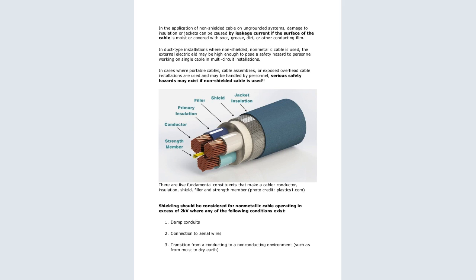And then shielding should be considered for a non-metallic cable operating in excess of 2 kilovolts, where any of the following conditions exist. Okay. Another one is the connection of aerial wires.